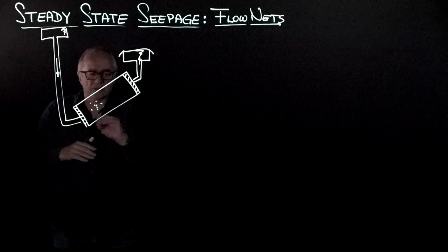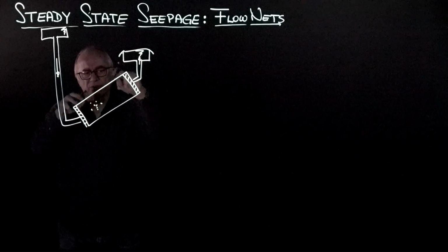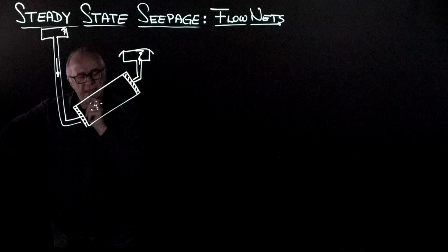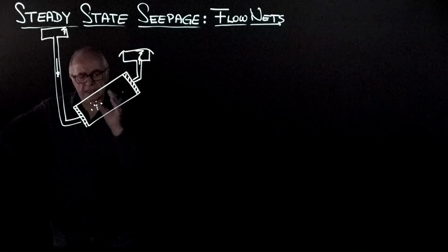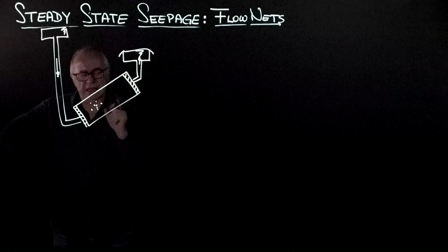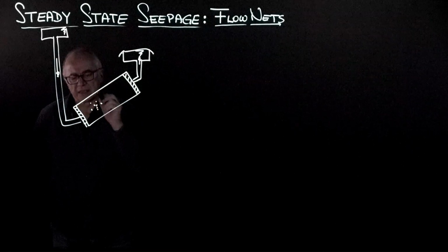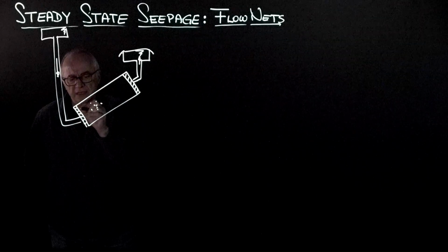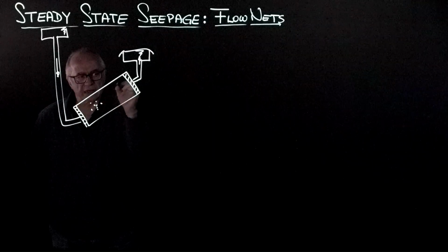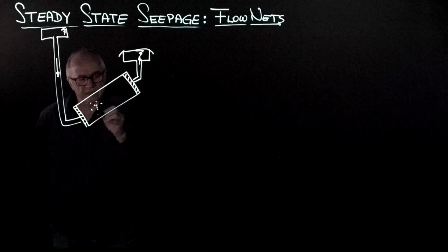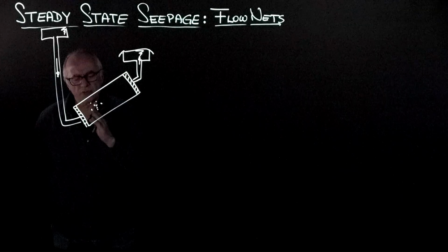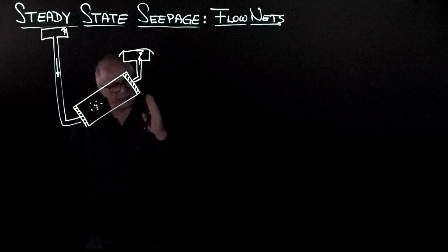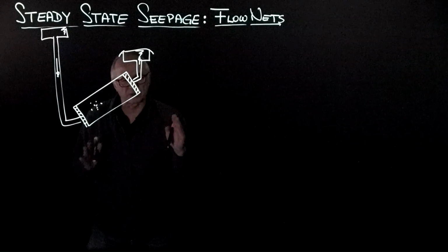So clearly this will be one extreme flow line, and that is the other one. Now, what about the total head at the entry and the total head at the exit? In other words, what is the first and the last equipotential? If you feel like a water droplet and you put a color droplet here, it will draw a line parallel to the boundaries, the same one at the bottom. So it appears that all flow starts on this boundary, ends at that boundary. That gives you quite a good idea of what the first and the last equipotential will be.